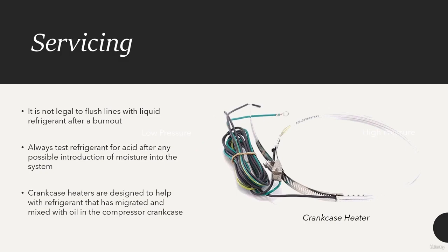A few notes when servicing refrigeration equipment. It's not legal to flush lines of liquid refrigerant after a burnout. You should always test refrigerant for acid after any possible introduction of moisture into the system. So any repair work where the system was opened up is a potential for moisture.